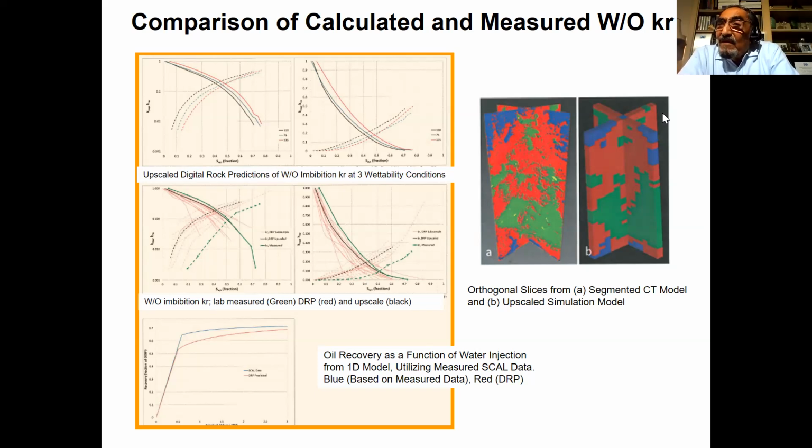So I designed equipment with a large diameter core, and we first did the process of gas and water movement in the reservoir and trapping the gas, and the trapped gas saturation was around 50–60%, because of some of the rocks, which is moldy limestone. Then we have to reduce the pressure, because as you produce, the trapped gas in the trapped zone expands. And we found out that if the reservoir pressure drops significantly as a result of production, some of this gas expands, and when the saturation gets 3–4% beyond the trapped gas saturation, the gas mobilizes.